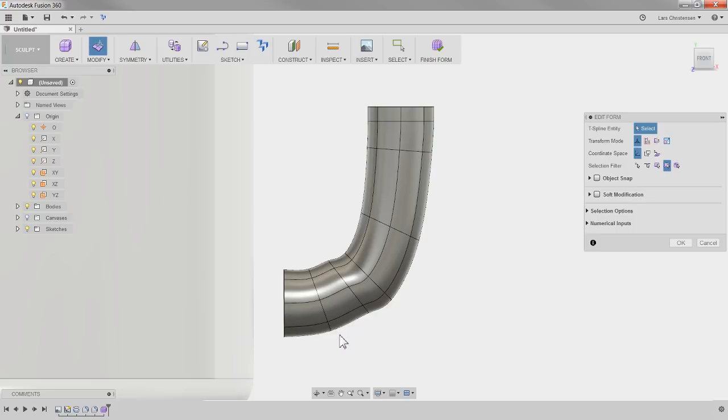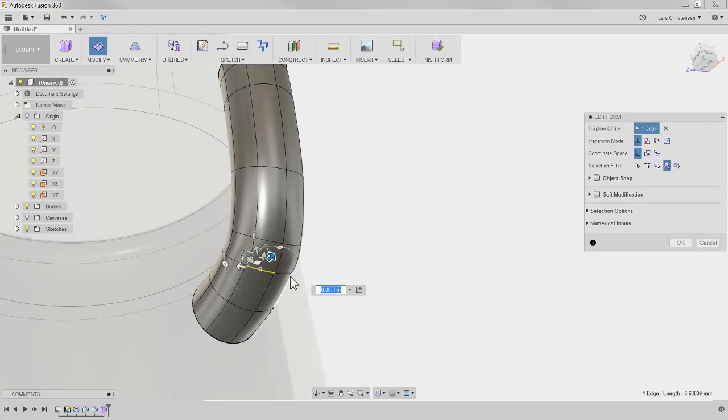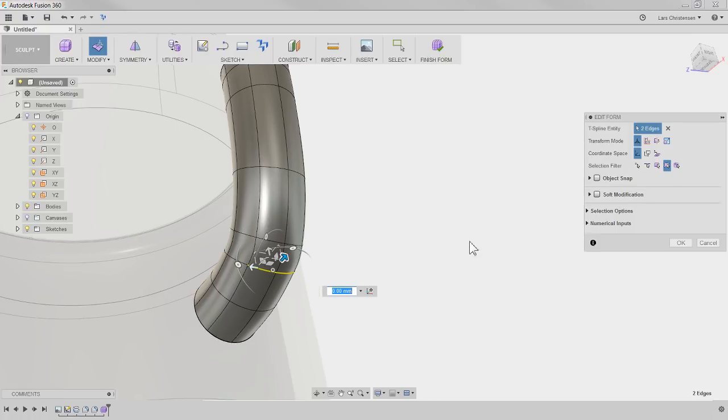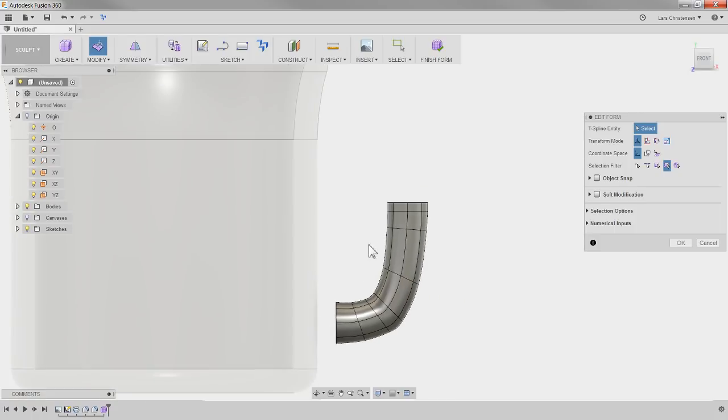In this space, you can at any point click on these different segments, and you can try to straighten things out a little bit on these rings, and I can try to get unified segments. I can also just select a couple of segments. So I could go in here and select these two edges by holding down Control. And now if I go back to the front edge and I start pulling in those, I'm really only pulling in those two lines. So that is really how we will work with this.